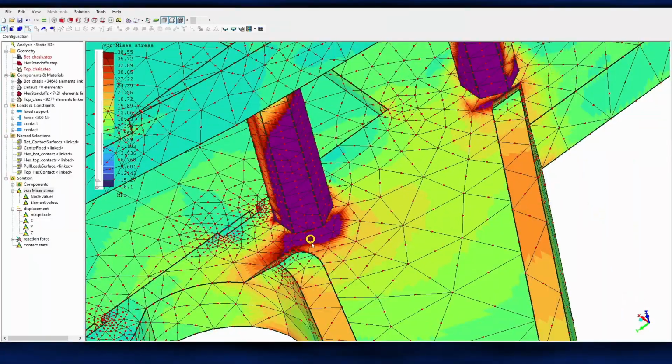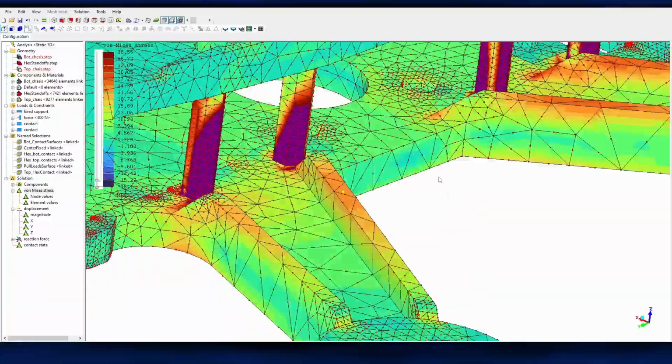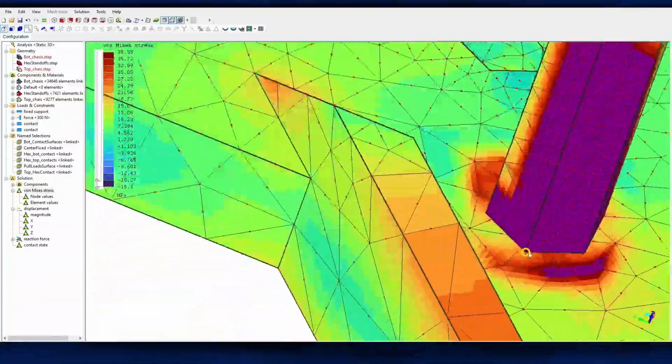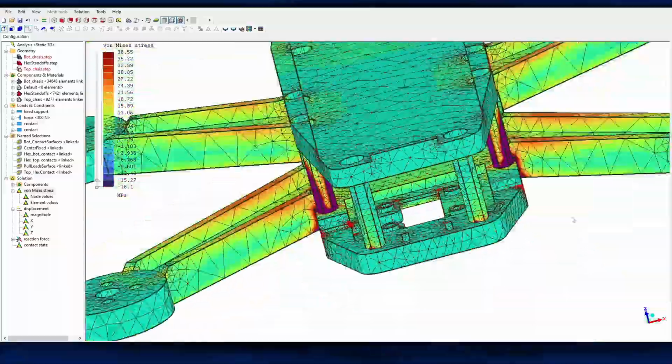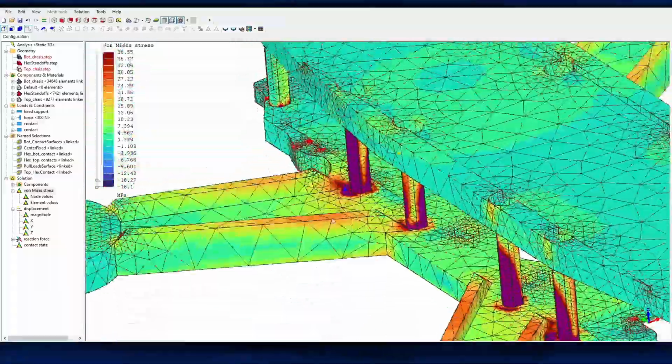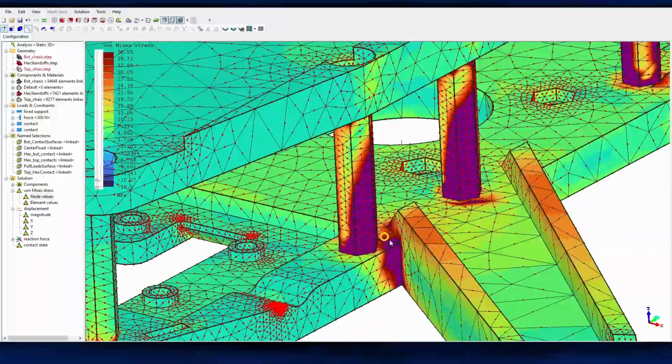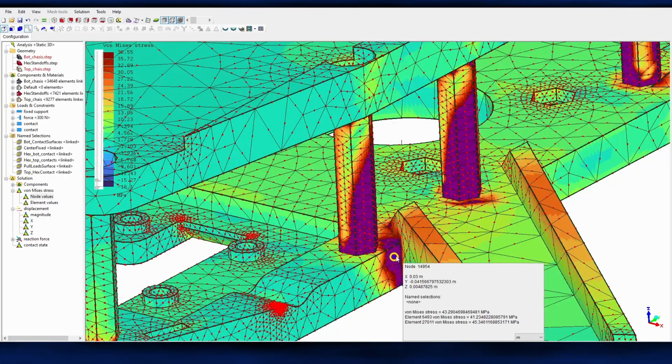Earlier, we set our max stress for the PETG to be around 30 megapascals, so areas that exceed this value would be considered as hot spots for further analysis and making changes to the design if necessary. Looking for these areas, I found max stress mostly in the sharp corners of the arm connections, and where the standoffs are holding the part.